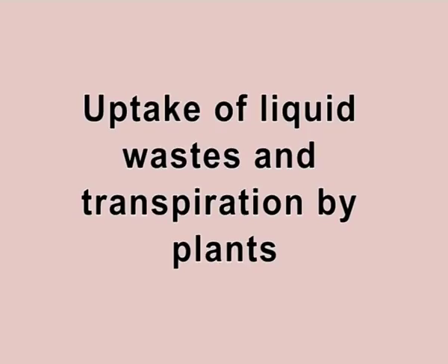Adsorption of organics in the soil particles and uptake of nitrogen and phosphorus by plants and soil microorganisms is another additional benefit. And another one is the uptake of liquid wastes and transpiration by plants. Percolation of water to groundwater also contributes in the irrigation process.